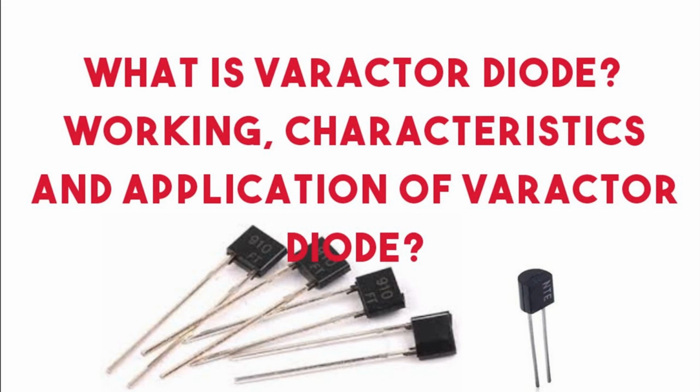Key features and concepts of voltage-controlled filters include: 1. Filter types. Voltage-controlled filters can be designed using various types of filter configurations, such as low-pass, high-pass, band-pass, and notch filters. Each type of filter affects the frequency content of a signal differently. 2. Cutoff frequency control. The most common parameter controlled by voltage in VCFs is the cutoff frequency. The cutoff frequency determines the point at which a filter starts attenuating frequencies. By adjusting the control voltage, the cutoff frequency can be shifted, allowing different frequency ranges to pass through the filter.